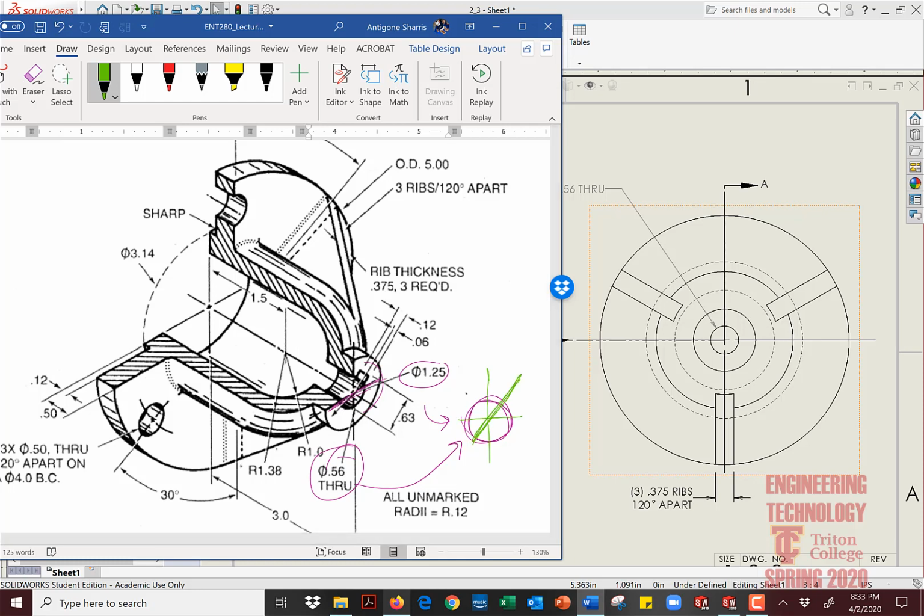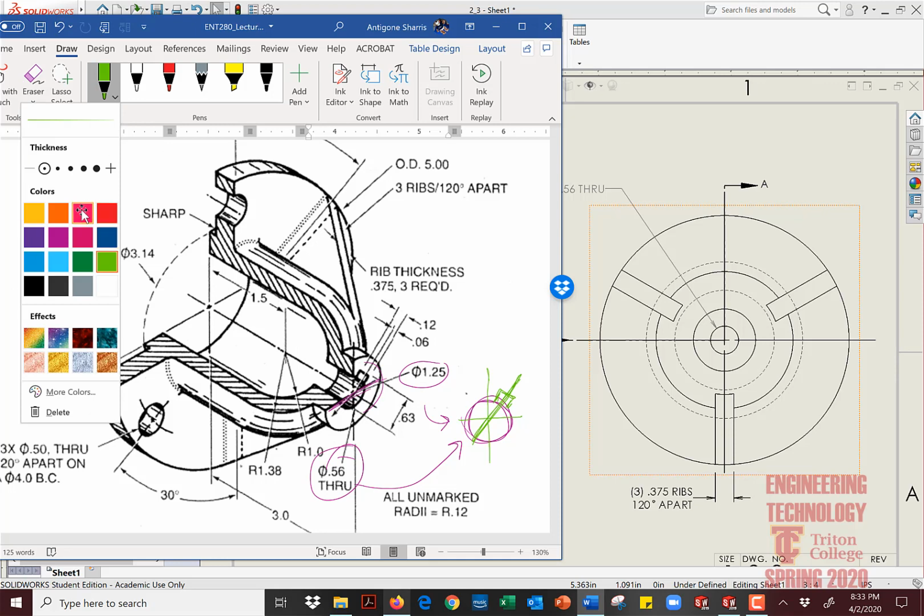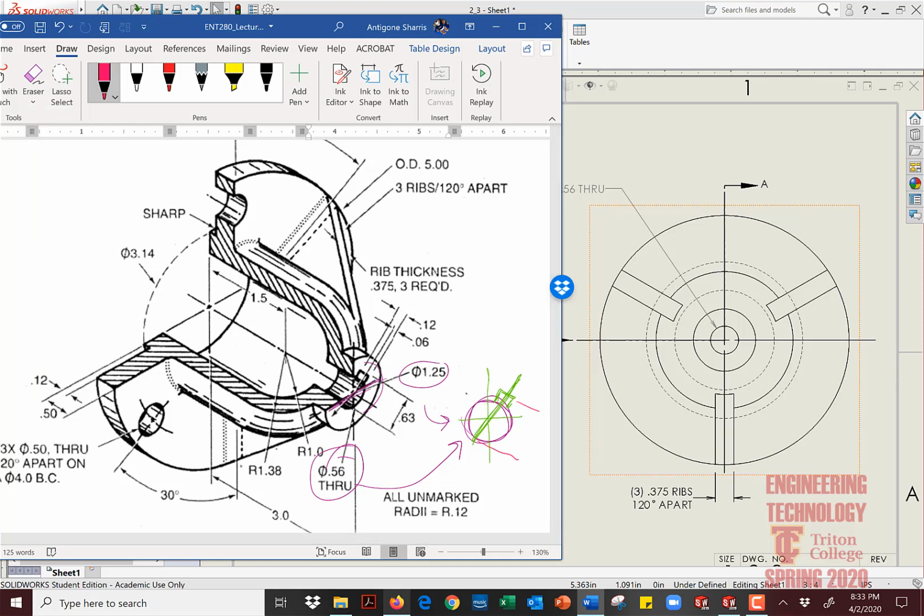And you're creating a line at an angle, and that is where you're going to add that keyway. And the dimension of that keyway, this dimension from the back edge of this arc, aligned with this line to the front of that keyway, that is 0.63. That is this dimension right there. Okay, keep that in mind. Okay, erase a few things. See, this is this dimension right here. So to account for that, okay, that's how you have to build a sketch in to build that.